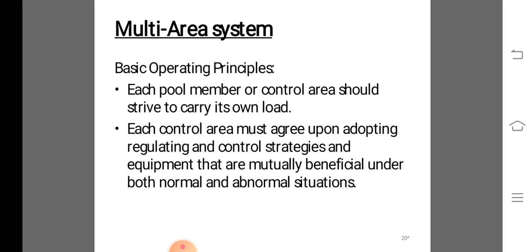For this purpose, considering the relatively larger time constant of the power system, the governor action can be neglected, treating it as instantaneous action. Then the turbine generator dynamics may also be neglected at the first instant to derive a simple expression for the time response.